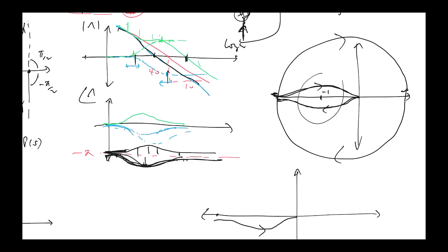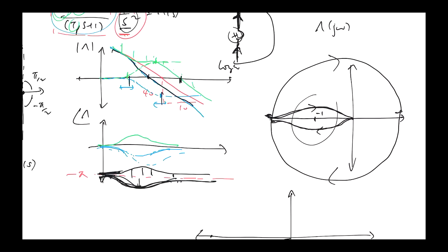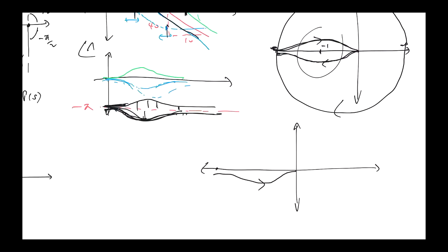So we've gone up this part of the D contour, right? Now we're going to go around the bit at infinite radius. You get stuck here. When you go up the negative imaginary axis, you come out the other side like this, the mirror image of what you had before, okay?